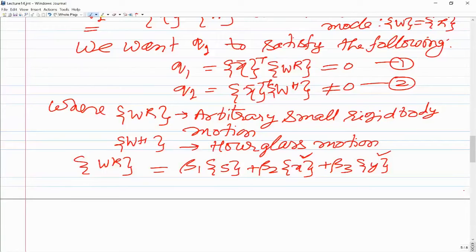So let us take that as a combination of this vector h, which is alternately plus and minus 1 at the nodes, and the combination of derivatives of the shape functions integrated over the area of the element with respect to x and y. So this hourglass shape vector